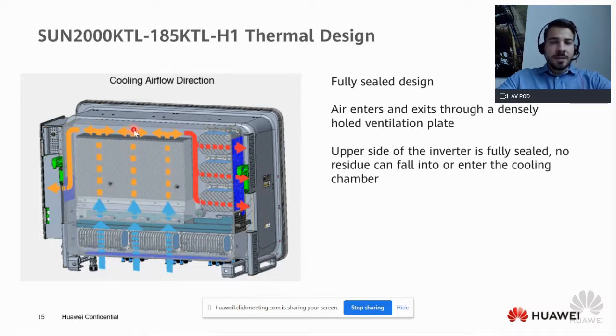It means no leaves and no materials or residue can build up on the upper side. The air can only exit through these 2 ventilation plates on the left and right hand side. This is how we can guarantee the cleanliness and the maintenance freeness of the inverter.